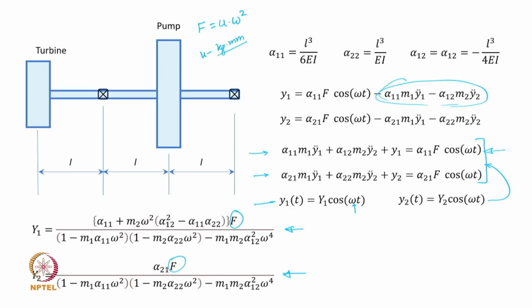Okay. You convert that into kg meter and then use appropriate rotational speed omega to get the F value in newtons, and expectedly the amplitude with which the discs 1 and 2 will vibrate, that is dependent on the strength of the amount of unbalance in the discs.